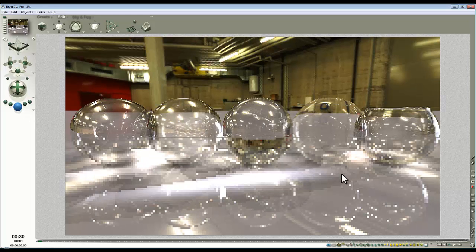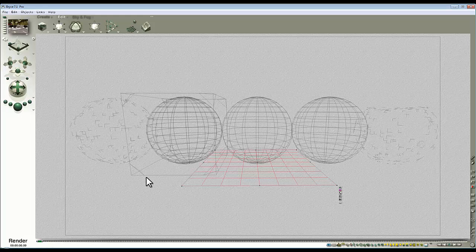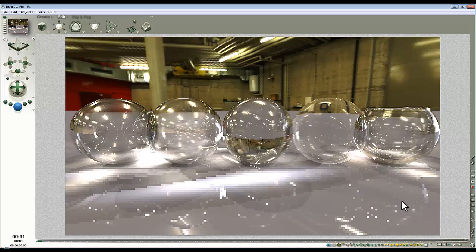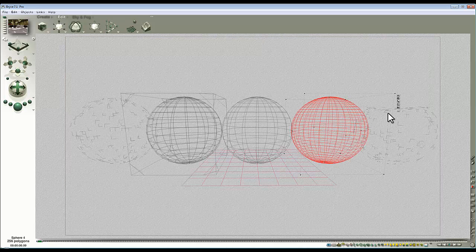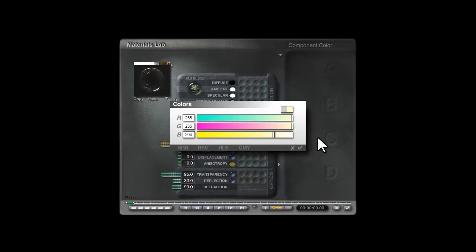It might be a bit too much because it's reflections everywhere. Let's take that really down to 5. And then we're going to have to start thinking about using premium effects like dispersing the reflection on the ground surface but remaining sharp reflections on there. So if we wanted sharp reflections on the materials, you've got to bear in mind that the specular halo will be the thing that determines how sharp they are or how blunt they are.